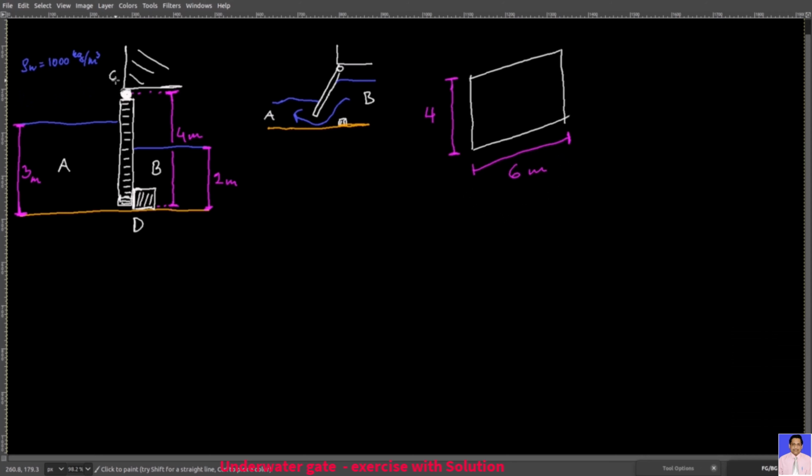As a result, two reaction forces are produced, Cx and Dx. So you can see that the gate is not going to swing open because of this stop block. In the hinge C, you have Cx, and due to the block at D, the gate experiences this force Dx. You cannot have vertical forces because the load distributions from both sides due to water are perpendicular to the gate, which means that they're horizontal. And so, what are Cx and Dx?